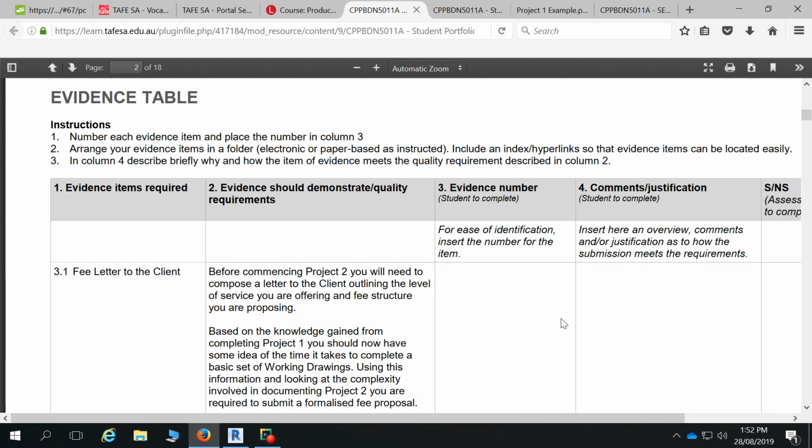Has anyone worked with or understand Hebel power panels before? I had a go at it in planning approval because I've never used them before, so Merrin showed me a little bit how to draw it in Revit. In terms of drawing the building, it's just a matter of putting the panel on the stud with a top hat, so it's not that hard to set that wall up.